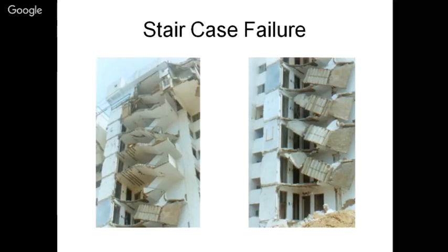So in that case, what we can do is provide the staircase structurally independent of the actual RCC structure. We can completely disconnect this staircase structure from the actual RCC structure, keeping just a little bit of structural connection between the two.